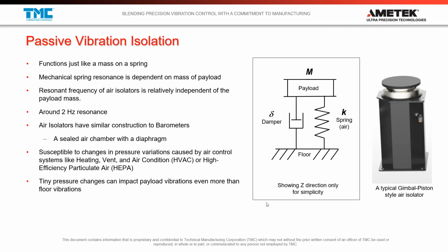Passive vibration isolators, like the piston type isolators we mentioned before, or springs with oil around them, even rubber elastomers, they all follow this sort of rule where there's a resonant frequency and then a roll-off at higher frequencies. And one thing that's always true is that they're dependent on mass.